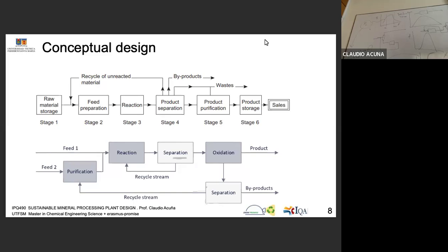But then when you finish the operation, you have hot liquid. You have liquid with a lot of pressure. By the way, in the autoclave reactor, all this energy, we call it enthalpy, hot and pressure, is used to generate steam. To cool down, generate steam, and steam is energy. In general, we use a lot of steam because it's an easy way to transport energy, thermal energy. Okay?